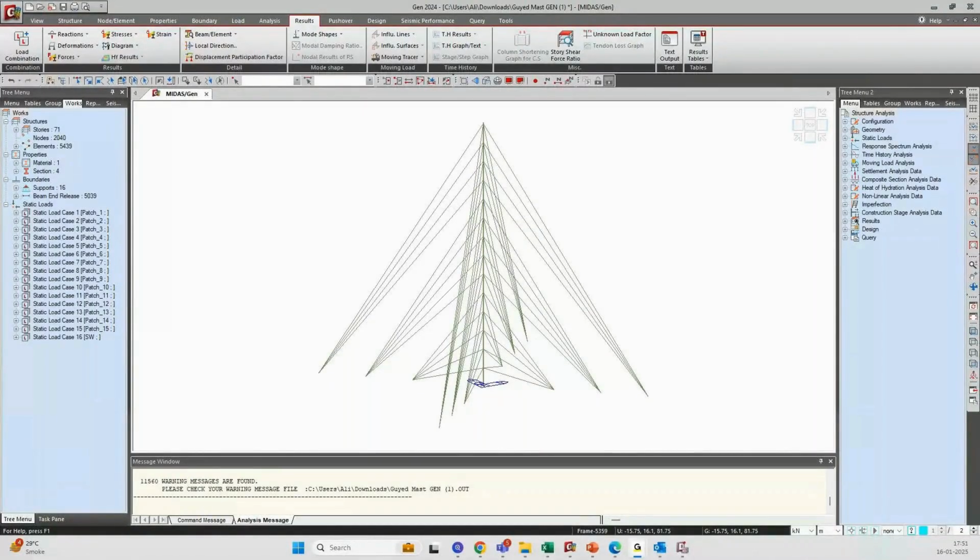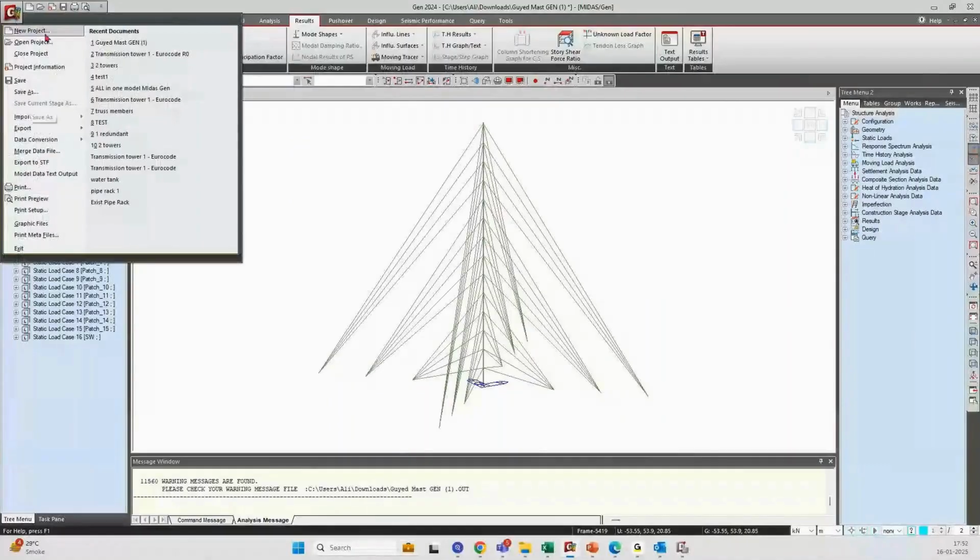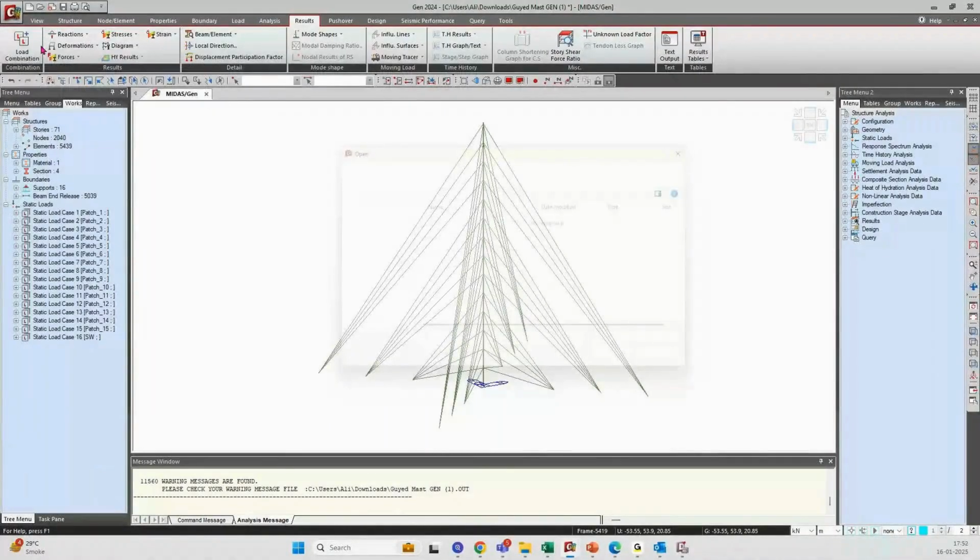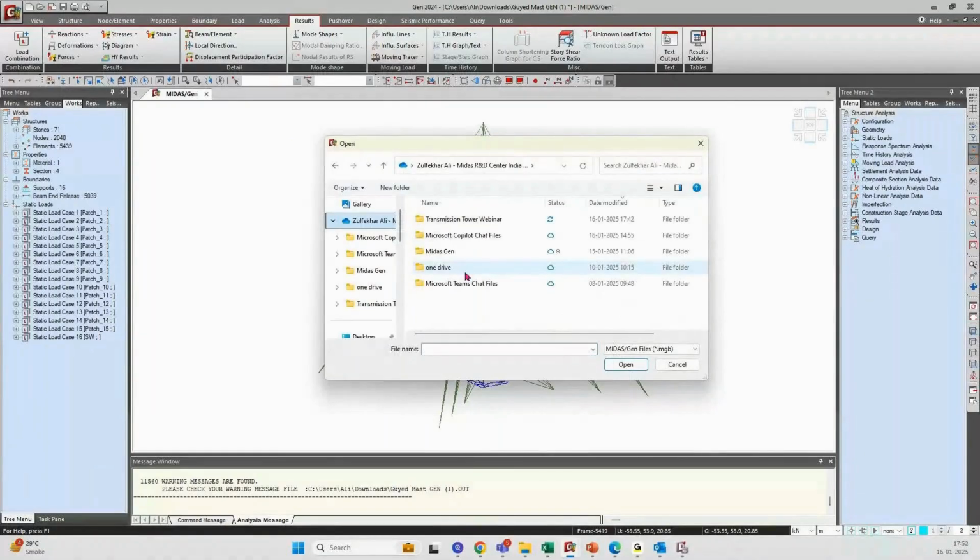How do you counteract the effects of overturning moments during the design? Okay, so in most of the cases, these particular structures have pin support conditions. But if you still want to see the moments for different combinations, you can create some load combinations, which are helping the structure to be stabilized, like dead load. Okay, and other load combinations like lateral loads which are trying to create the overturning. So these things we need to do a little manually.